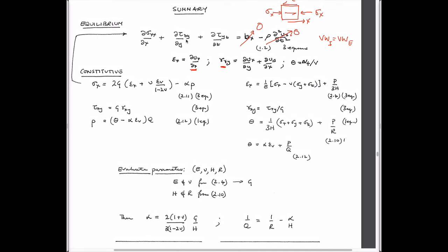Equilibrium equation. We said that to solve any boundary value problem, we need four conditions. Really only three important ones. Well, you need an equilibrium equation, mass in, mass out, or the equilibrium equation which we have here, which is basically this. We have to have a constitutive equation, and we've never written it in this particular form, but the constitutive equation says that sigma equals D epsilon is the way we've written it.